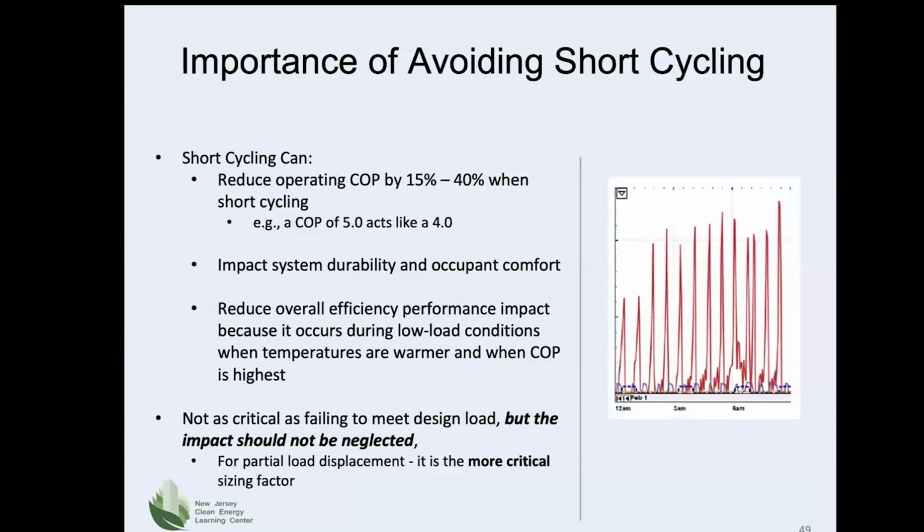By reducing the overall energy performance during low load periods, that also contributes to lesser efficiency. And by this, we mean when the outside air temperatures are warmer and the load is lower. Under those conditions, a right-sized unit, particularly one that's capable of adjusting to lower loads and lower levels of operation, can recover these parasitic losses from running a piece of equipment that's much larger than what's needed to meet the load.